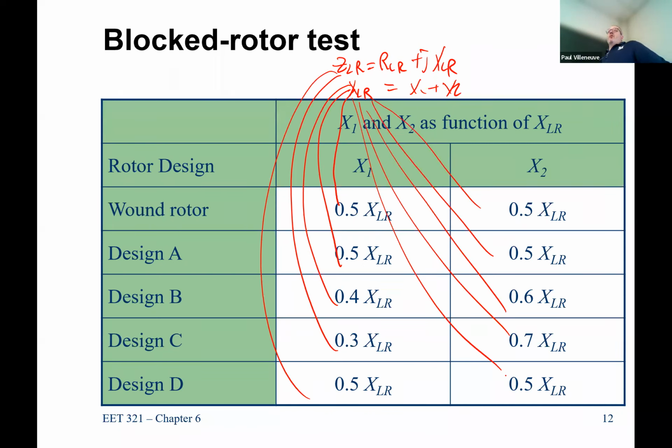These are the tests that you would perform if you're doing factory acceptance testing and actually getting test data. Because remember, the designers figure out how many turns of windings, what metal I use, what is the pitch that I need, how do I have the spacers, what type of magnetic material I use, et cetera, et cetera. That's all well and good. But when I actually energize the motor, I want to know that its characteristics are what I expect. So I still will put it through its paces, unless I've got it designed so well that these parameters never change, then I wouldn't have to do the testing. But this is the test.